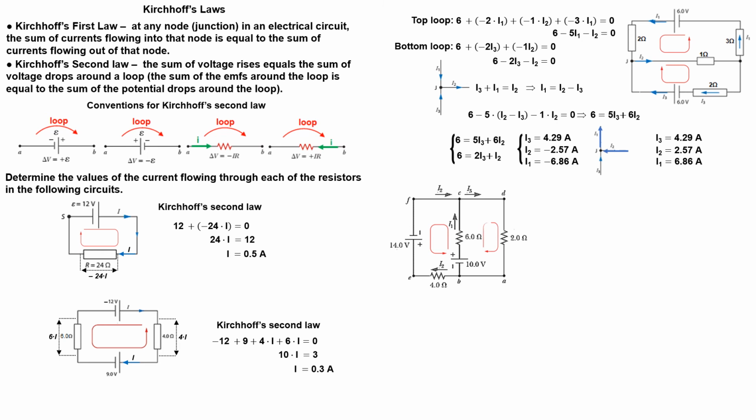When you have a circuit with more than one loop, start by applying Kirchhoff's first law to some node. This will simplify the next equations because it reduces the number of currents that need to be found. We apply Kirchhoff's first law at point C by writing... Let's start by looking at the left-hand loop. We traverse the loop in the anticlockwise direction. Applying Kirchhoff's second law, we obtain the equation.